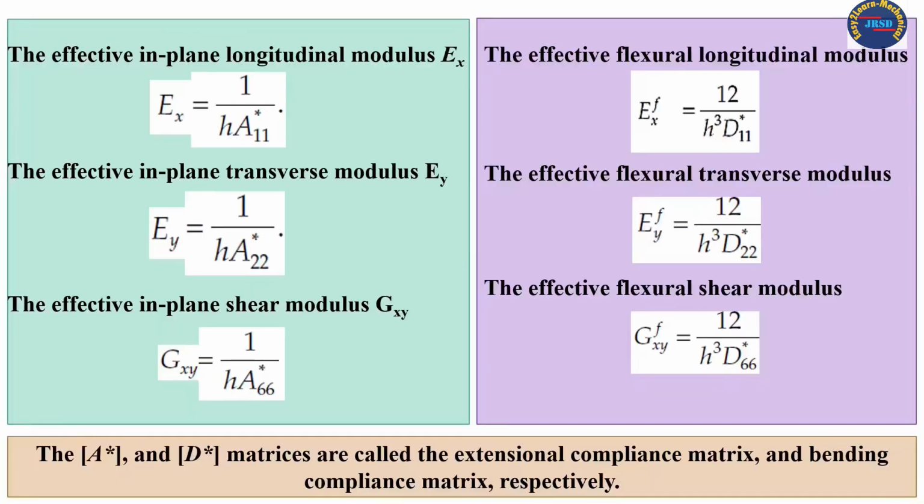By using that relationship, we can write the equation for the effective in-plane longitudinal modulus. The next one, to find the effective in-plane transverse modulus, we can use this equation. Then to find the effective in-plane shear modulus, we can use this equation. On the right side, you can see the effective flexural modulus formula, the effective flexural transverse modulus and the effective flexural shear modulus formulas.